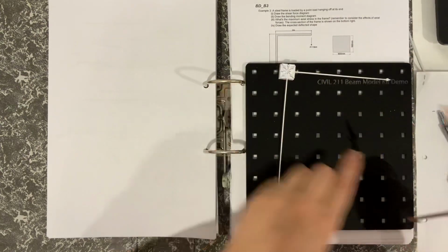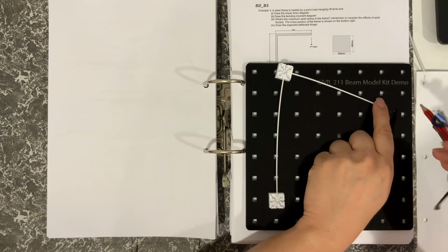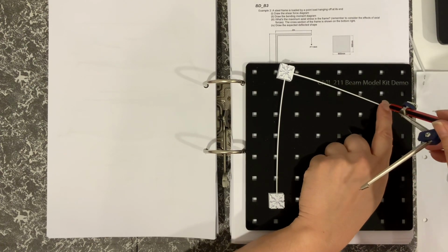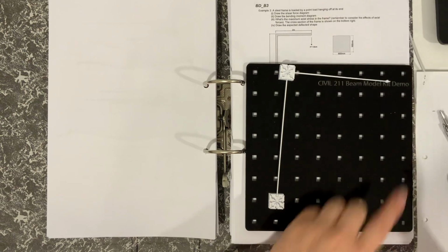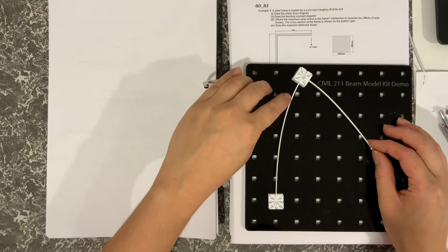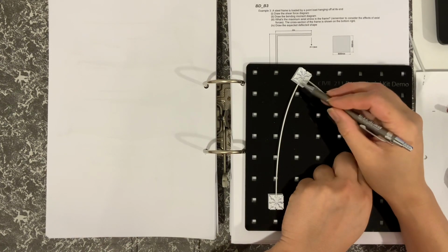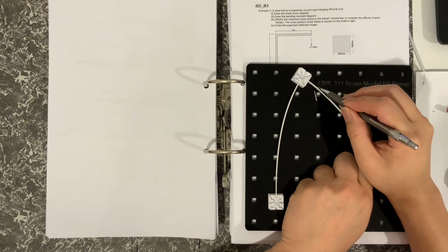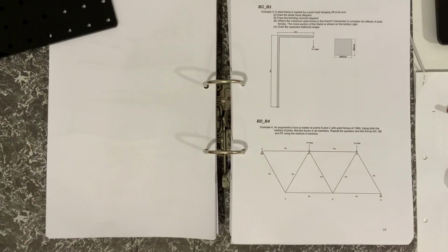And you can see this guy here, the bending moment at the end is obviously going to be 0 because it's a free end, and then it would just increase up over here to the maximum value. And we see here that that side's in tension, so that means the outer side's in tension, which means the outer side here must also be in tension with the same value. So let's have a look at what we've got there.